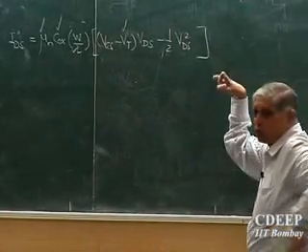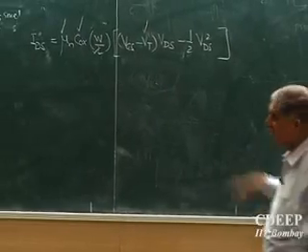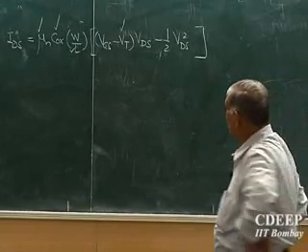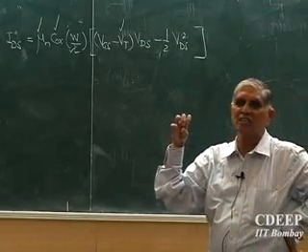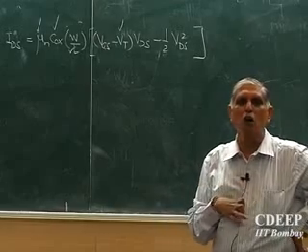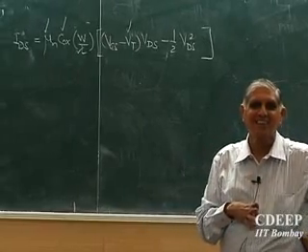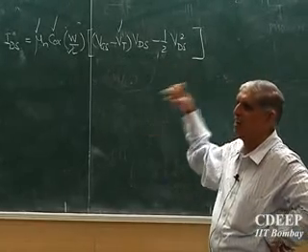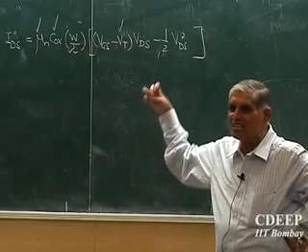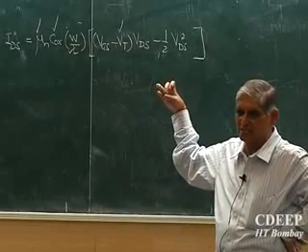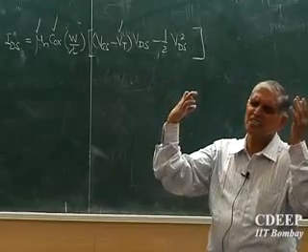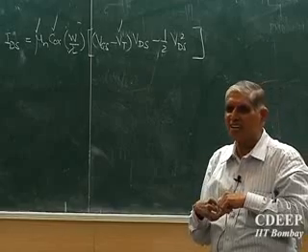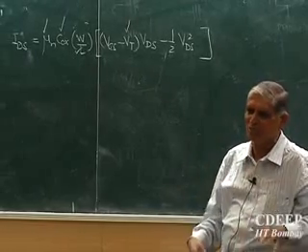Now before we go to the real analysis, we can see whether this itself is the accurate expression or not. We will see whether it is right. This is called the ideal IDS, VDS, VGS characteristics, or also called the textbook model. What does that mean? Because the textbook gives this, we say textbook model. But in reality, this model is not valid. But to a great extent it works in circuits. So I say, okay, silicon doesn't understand physics, chemistry, maths, good, it works.